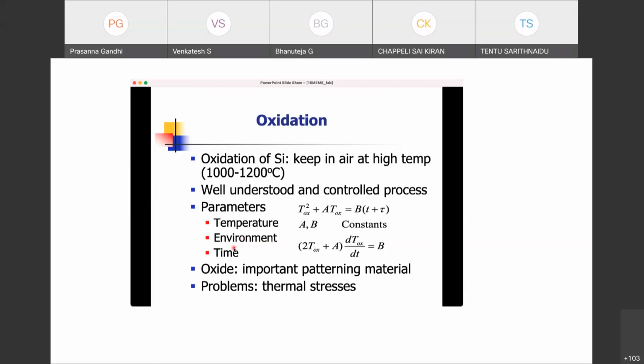It is used for a lot of processes in the fabrication of chips also. Typically the oxide is used as the gate material in the transistor. Things like that. Where you want some small layer of insulation, a very thin layer of insulation, you can get it by this oxidation process. So really nanometric size layers you can produce in a very nicely controlled manner.